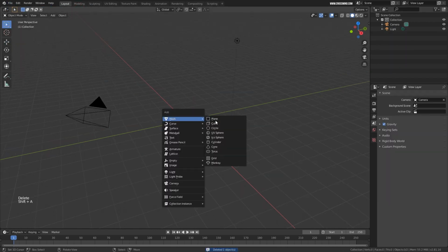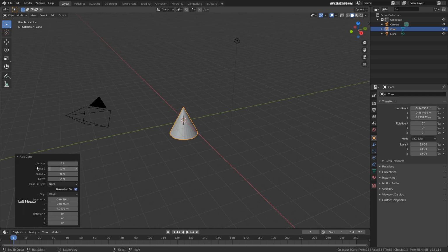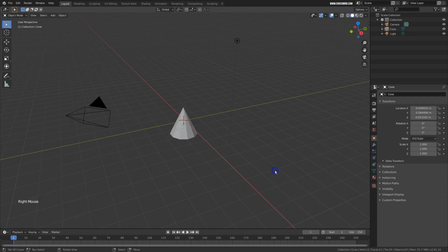One more thing, when you create new objects, let's say if I create a cone over here, now before I drop the object or use any other command, you can see this option is available, which can be expanded, and this gives you the option to tweak this newly created object. This option is only available immediately after you have made one object and you haven't dropped the selection. Once you drop the selection, that option is gone and you cannot change it.